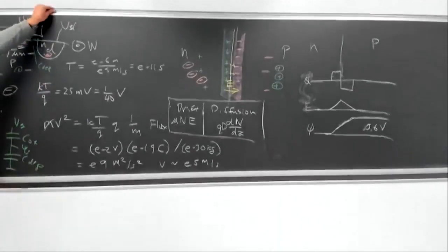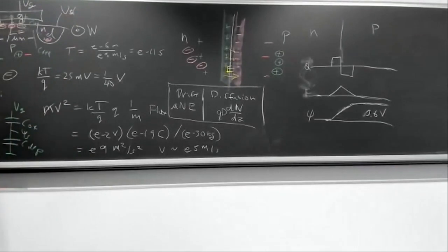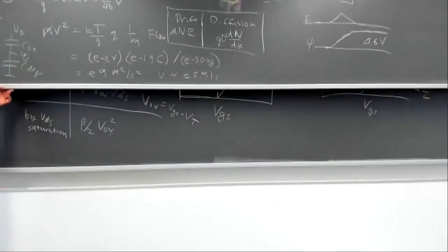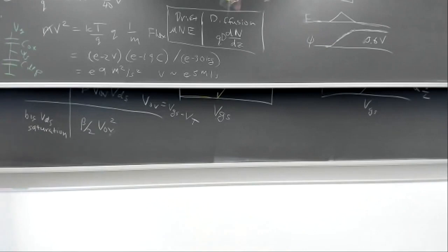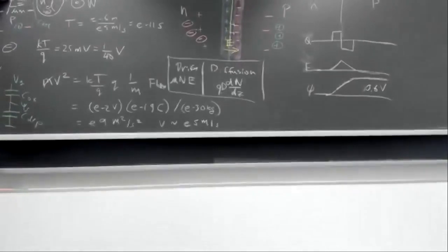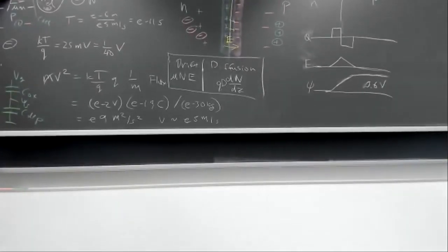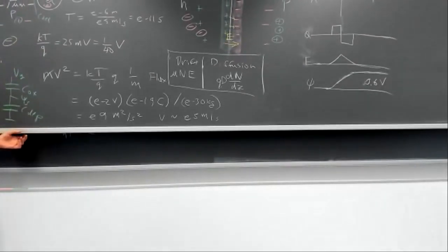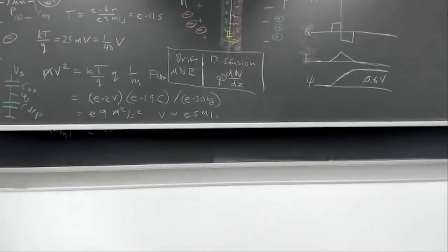Why are the mobility and the capacitance constant? The question is, why do the mobility and the capacitance appear in the linear region equation? Oh, it's not really constant. The capacitance is constant because it's just the gate oxide capacitance, which is on the order of around a picofarad per square micron. So mobility has a relation to the voltage, right?